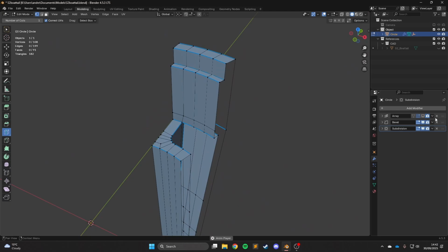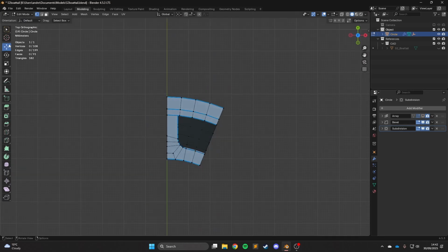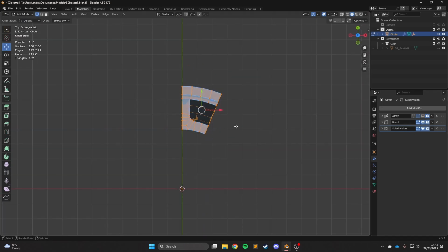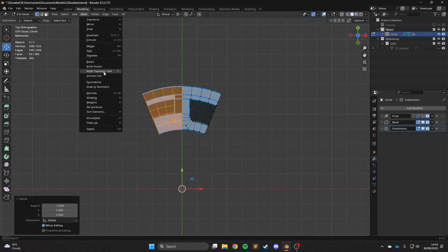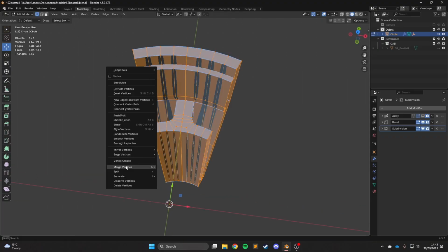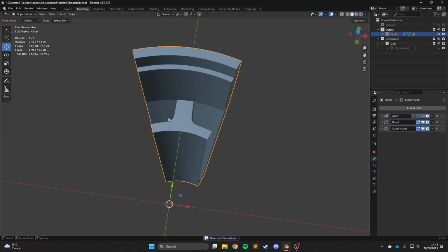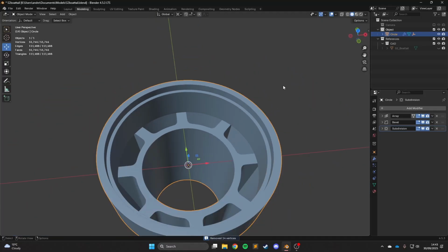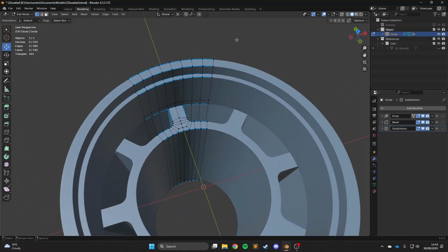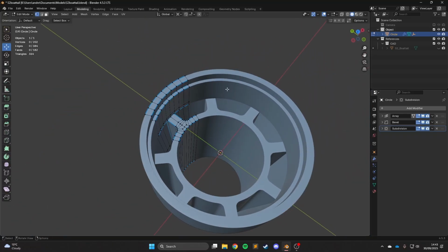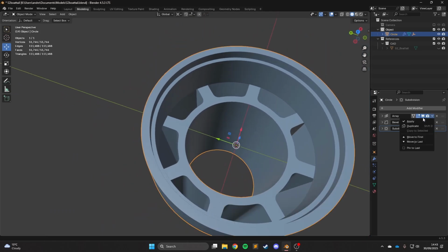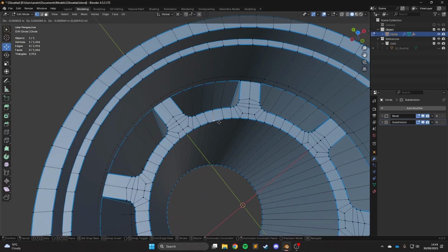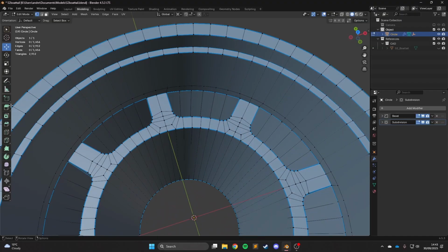Cool. And now, all we need to do is the same check we've done before. Set the cursor, then duplicate it with Shift D and right click, then S X -1, then Mesh, Normals, Flip. Then we're going to merge vertices by distance. We're just going to do it this way right now so you can actually see everything. And now we can array everything together. There we go. You can keep it like this, but if you were to export it or something like that, you would just apply that array and essentially you can see everything's automatically merged up like that. So there we go.